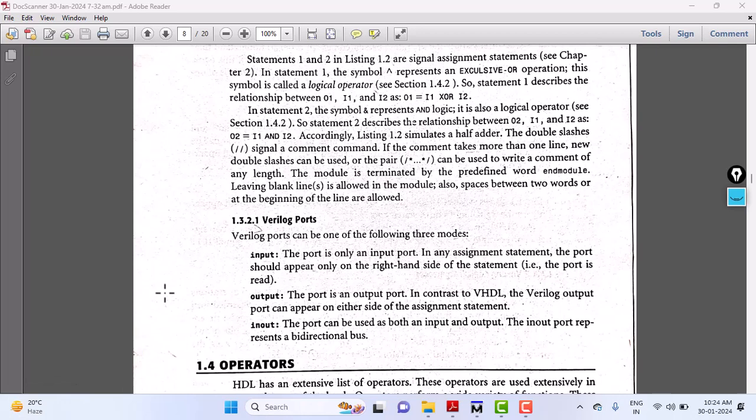You will see that when I show you the modeling of latches and flip flops, I will be using signal names with inout. We have a Q and Q bar. You remember in a latch, those Q and Q bar should be defined as inout because they are also outputs. They are also inputs for the other gate's input. Okay, that's why you must declare them as inout.